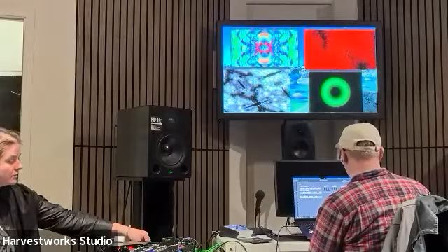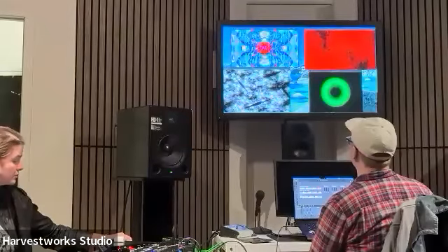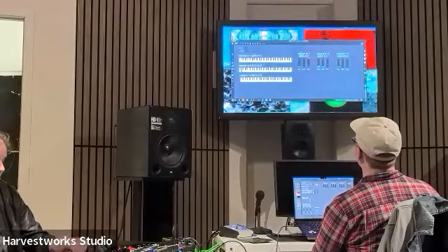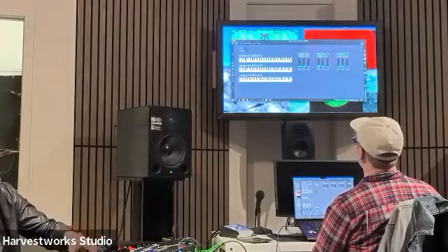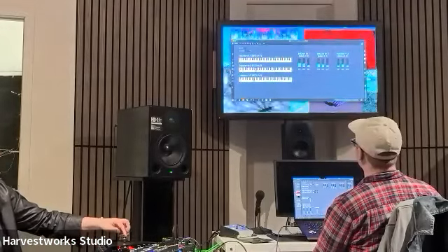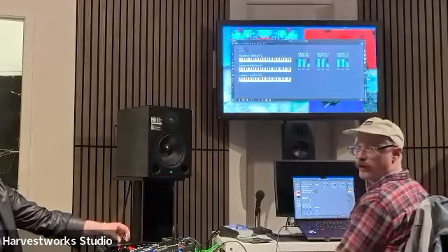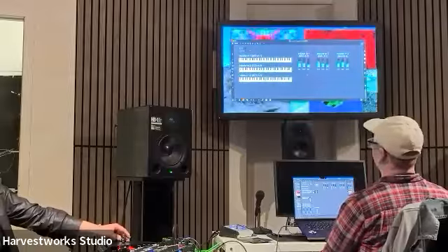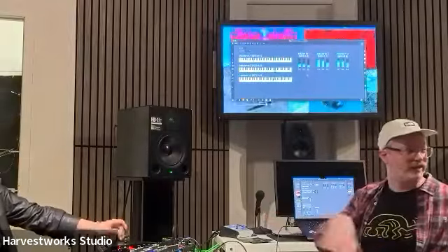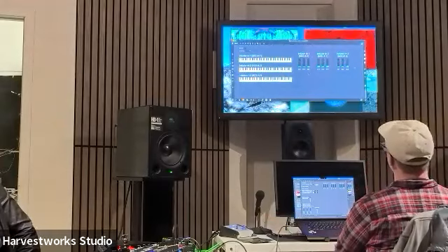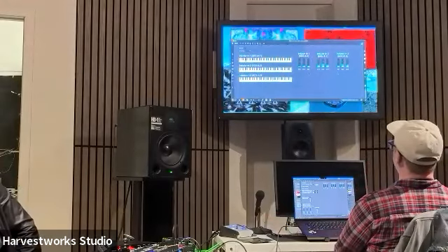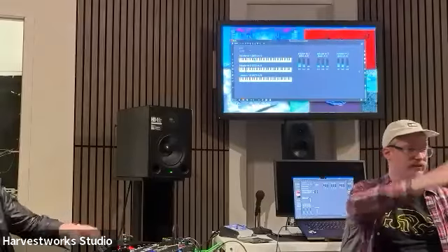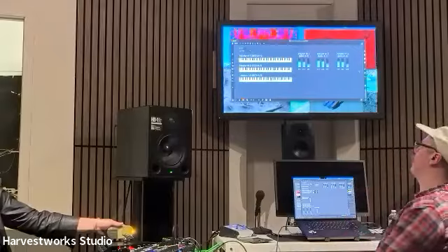This is a simple match dispatch just to show, in general, how it's working. This is the note data, channel 1, 2, 3. This is the CC data I was talking about, 4, 5, 6. As we give it signal, you can see it's going up. The notes are in the range of a grand piano, because it's more practical, since not all synthesizers are going to have notes going the full range of the MIDI protocol. As a visual person, I use the CC data because it's a digital version of the control voltage. It's a continuous 0 to 127 signal that I mapped to different parameters.